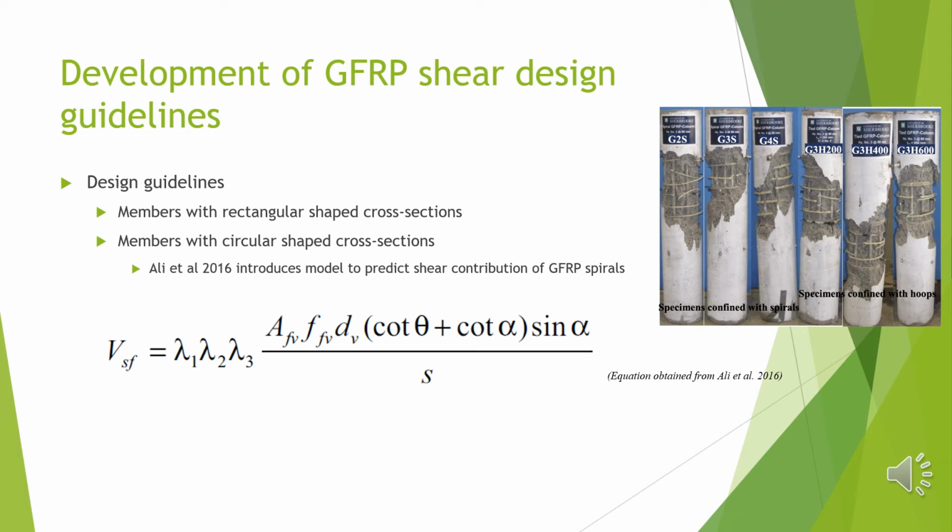In 2016, this use was determined, along with equations and methods for the use of GFRP in the construction industry, and an experimental factor of 1.17 was developed for shear elements.